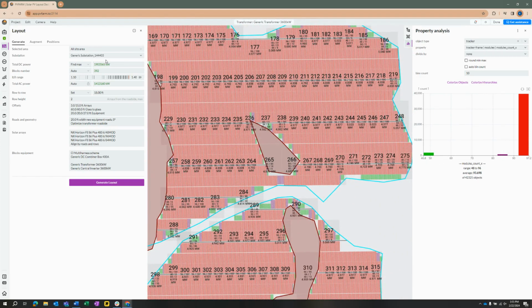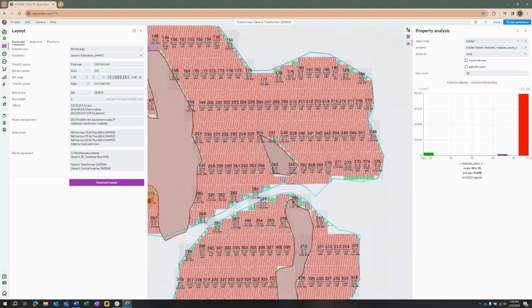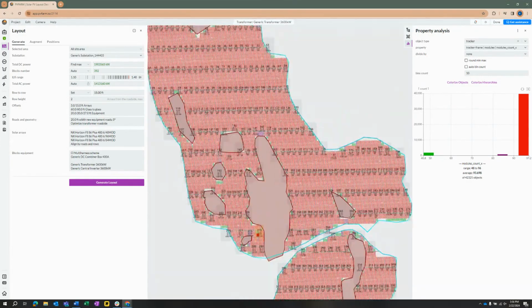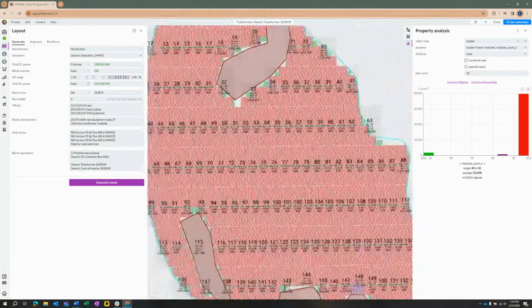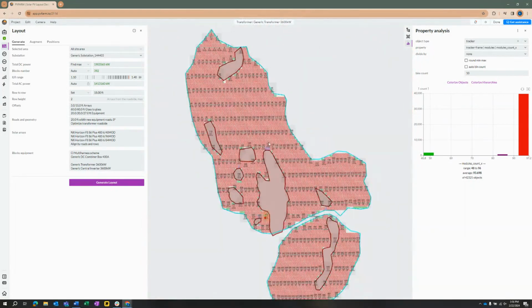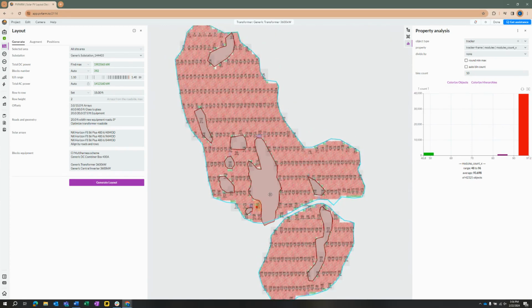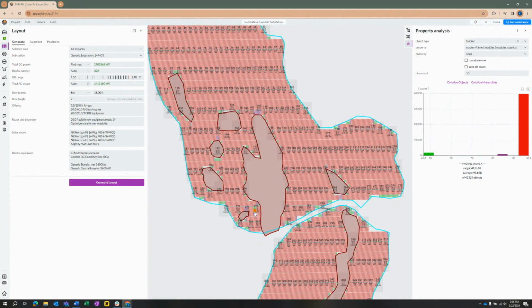Of course, it is always a trade-off of trying to keep the highest DC power with the least amount of configurations. We could even add a 4th configuration if we wanted to fill some of those gaps in. We could bring one of those 70s or even the 54 back in. But I think for the purposes of this demonstration, let's go with our selected trackers being 48 length, 84 length, and 96 length.